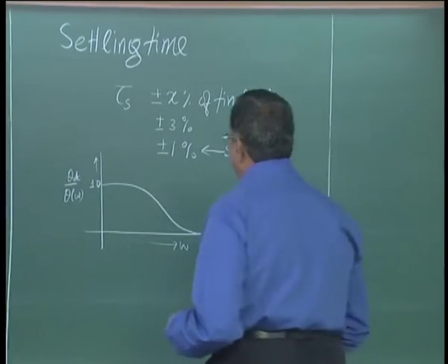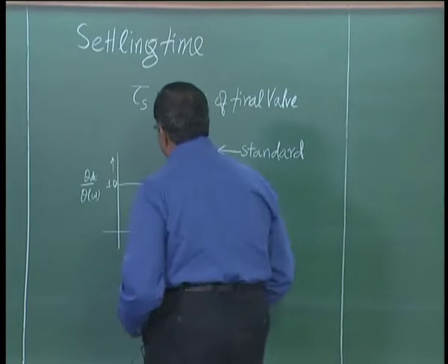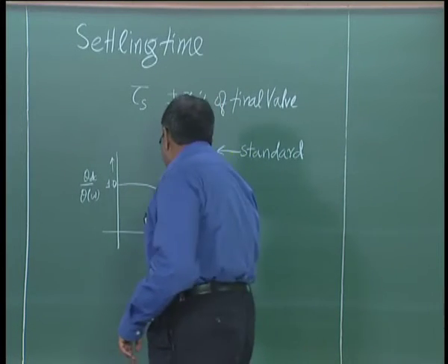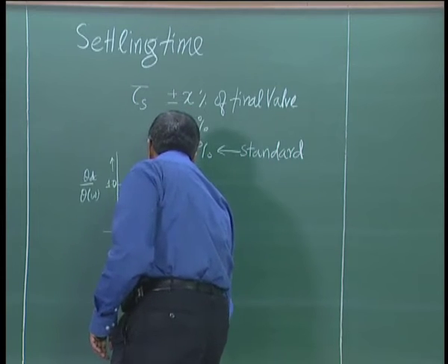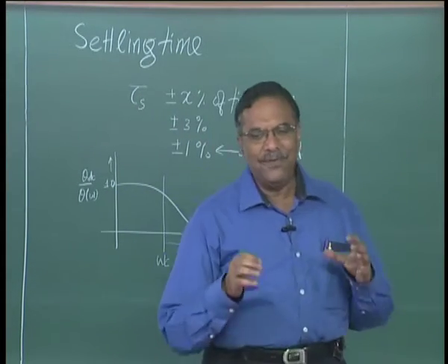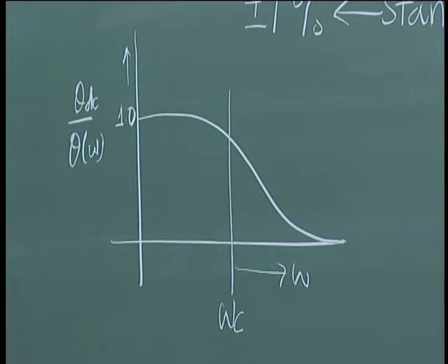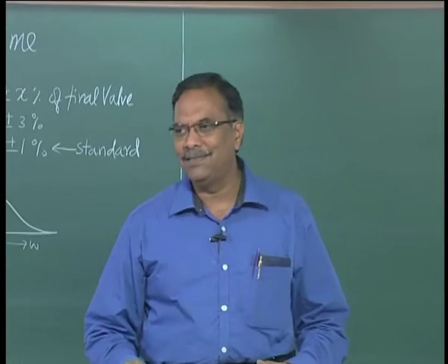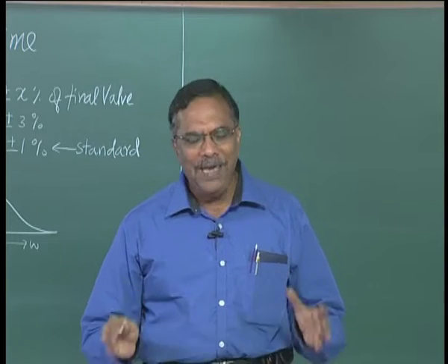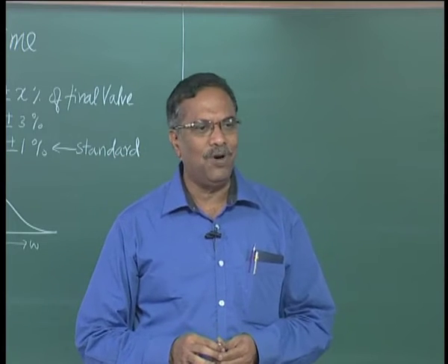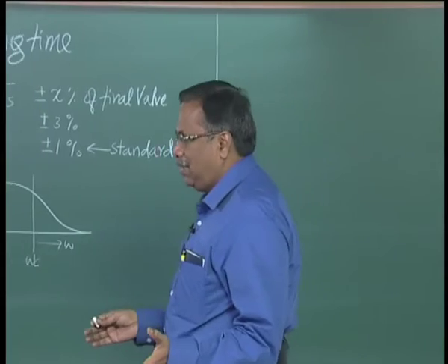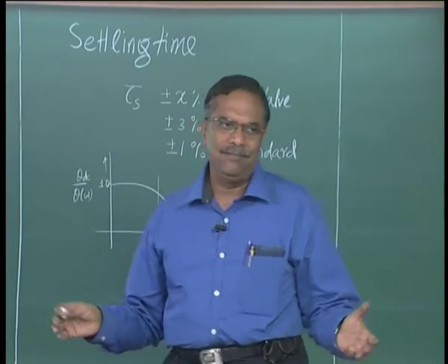But if I look at it as a system, then it will have a low pass function with a cutoff frequency omega c radians per second, right. Because it is a physical mechanical system with springs and coils and the rotating arrangement, the omega c would be very very small, maybe in the range of 10 radians per second.